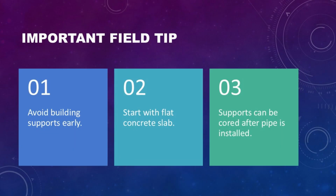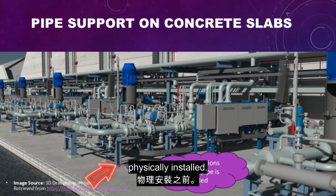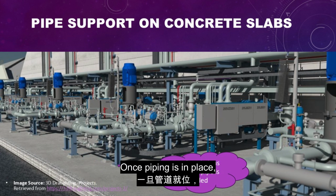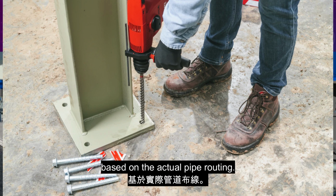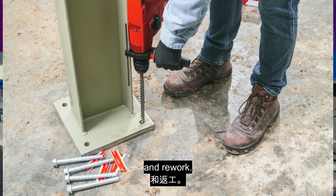Important field tip: never construct pipe support foundations before the piping and equipment are physically installed. Instead, civil engineers should design and build a simple flat concrete slab in the beginning. Once piping is in place, support foundations can be cored through and installed accurately based on the actual pipe routing. This approach avoids unnecessary assumptions and rework.